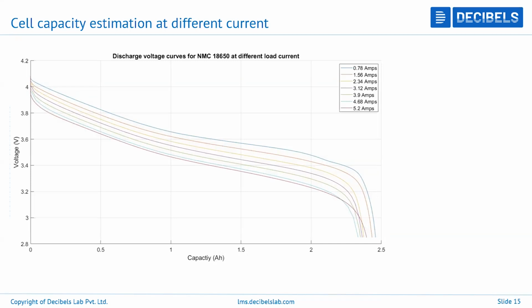This is again with respect to the chemical reactions occurring inside. At a certain rate of current, it's not going to be able to provide you the desired capacity anymore. So this is another parameter, which you can call the discharge capacity. This way you can visualize your discharge capacity. Once again, this will be used as an input into your battery pack control system to govern it in such a way that the capacity goes on getting adjusted as per the load.